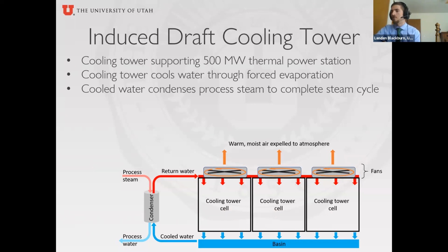They also were equipped with what we call VFDs, or variable frequency drives, on them. These are common for anything powered by a motor, where you might need behavior besides just binary on and off. So you can turn these fans down from 100% to say 75%. You actually get energy savings that way. So that's really important that they have that, and that's a very useful tool. And in theory, you could operate all 12 of these fans independently of each other at different operating points, but they don't actually operate that way.